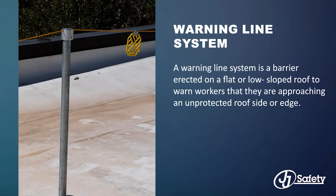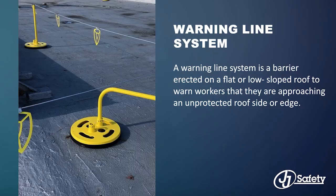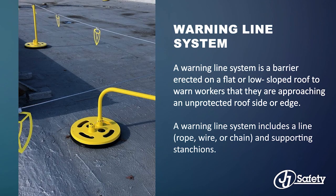A warning line system is a barrier erected on a flat or low-sloped roof to warn workers that they are approaching an unprotected roof side or edge. A warning line system includes a line and supporting stanchions.